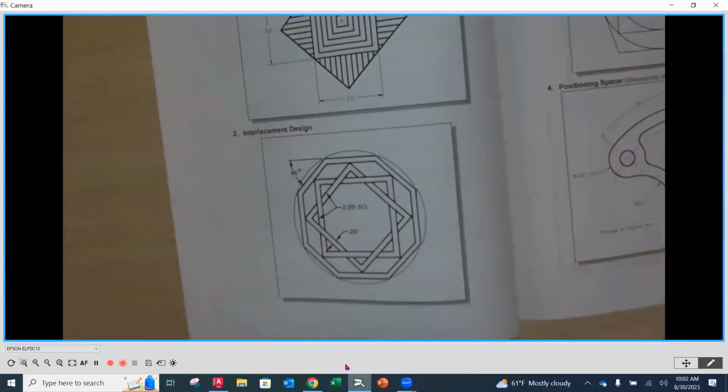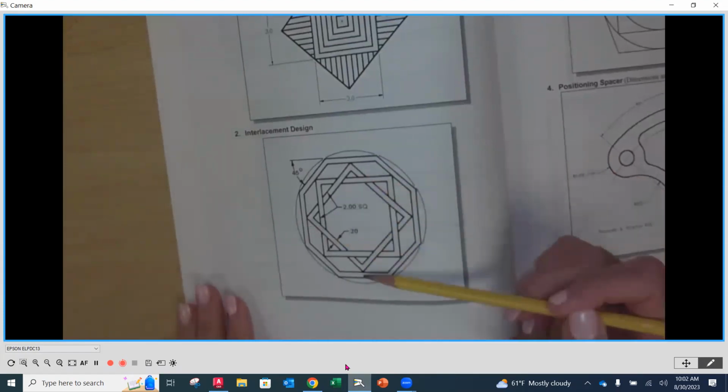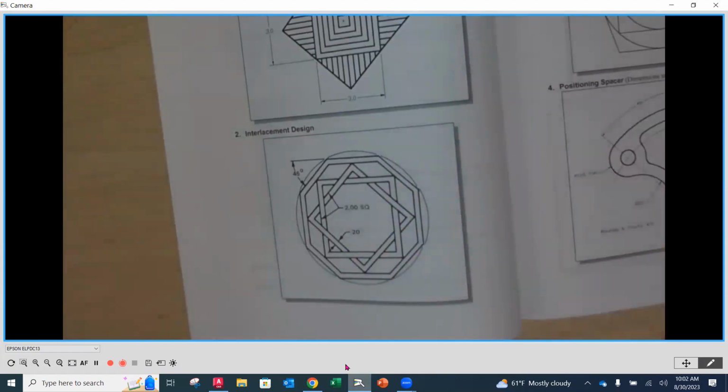We're going to create now another square, but it's going to be rotated 45 degrees. Now I could go back in and do the polygon with the offset and put it in at the 45 degrees, but I'm going to show you how we can use the rotate copy command to do this.